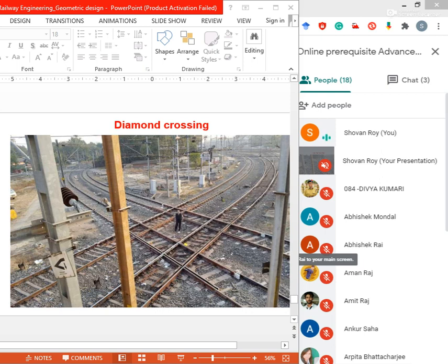Then wayside or crossing station. After a flag station comes the wayside or crossing station. While a flag station has arrangements for dealing with traffic but not for controlling the movement of the trains, a crossing station has arrangements for controlling the movement of the trains on block stations.